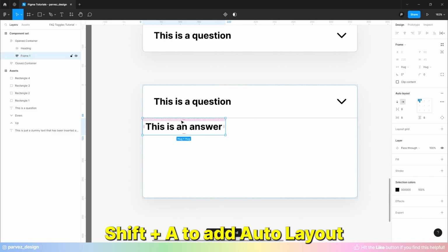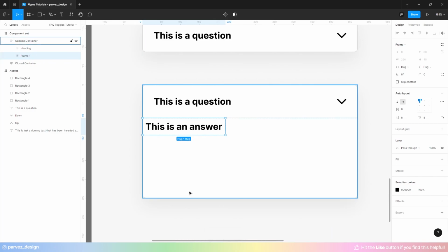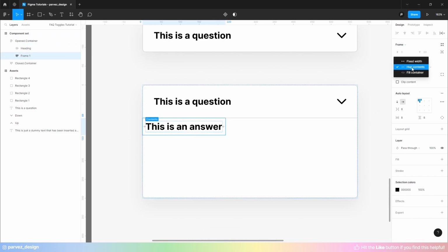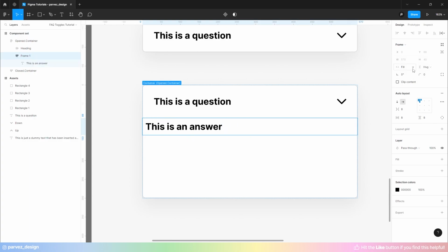So here we have our auto layout, and as before, let's set it to fill, but I'm going to keep the height as default, because we need to expand the height as we enter more text. So I'm going to keep it as it is, but for the padding I'm going to choose 30. And for the top and bottom padding I'm also going to choose 30.